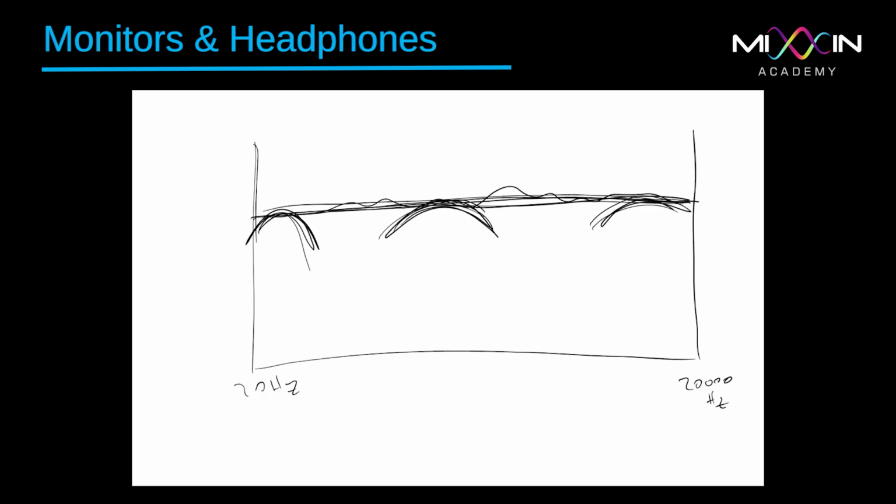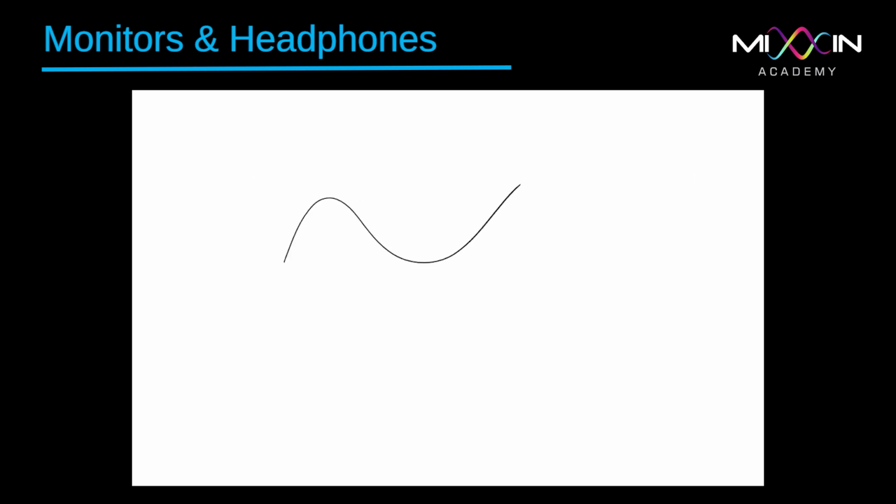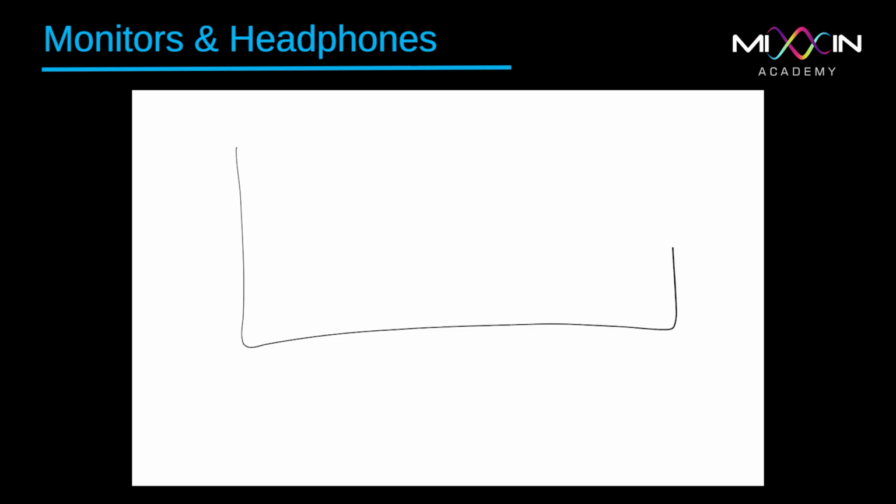Usually, this is produced by playing a sine wave sweep, meaning that the sine wave ups its frequency slowly, getting faster and faster. That way, we can see if that sweep inside the spectral metering is flat, if it's going to produce a flat signal. We record that with a microphone, of course, a flat response microphone. Usually it's piezoelectric. And this is how we measure.